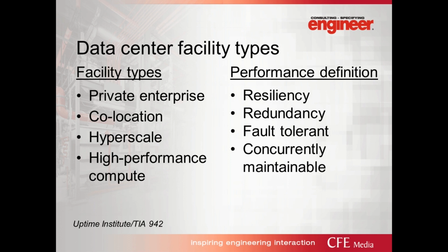Sometimes these aren't even considered data centers. They just kind of look and smell like a data center. But these are dense kW per cabinet facilities for number crunching. Oftentimes these are not as concerned about redundancy and just really need power and cooling for capacity purposes. And sometimes, they don't even require generators. So you have to understand not every data center is created equal, and you have to tailor your design towards that.